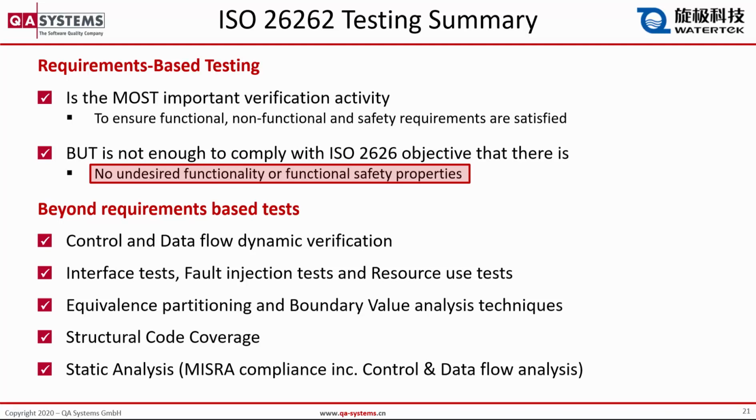So beyond requirements-based tests, we can look at control and data flow dynamic verification, interface tests, fault injection tests, and resource usage tests. With the equivalence partitioning and boundary value analysis techniques, with a safety net supplementing the whole lot using structural code coverage to make sure we have tested enough. In addition, of course, there is static analysis, not only for the coding standards compliance to MISRA, but also to support control and data flow analysis.